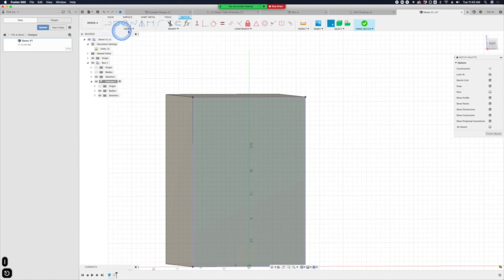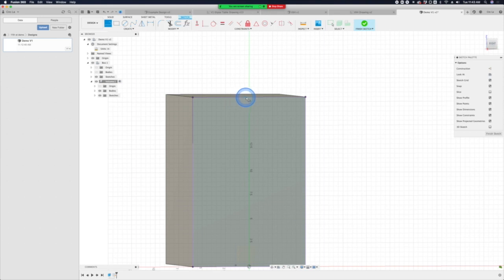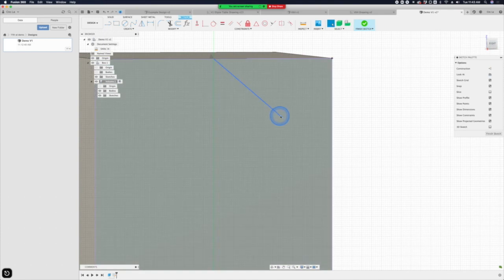Okay, so now I'm going to create a line, or L. I'm going to snap to that little triangle, which is your midpoint. I'm going to click there and drag this down. You can see that little square that pops up is keeping me perpendicular to that line, at a right angle. If you drag over here, that's why sometimes, if it's trying to snap, you can just throw this out into space anywhere. You can hit this green arrow to finish the operation, or just click and then hit escape will do it as well. So now this thing's just sort of floating in space.